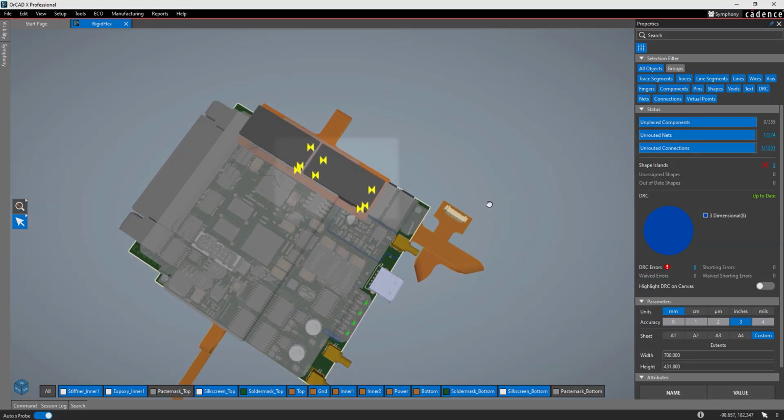These yellow DRC markers indicate collisions. At the full bend angle, the pins from the LCD in this zone hit the top cover and the chips below it. Bend locations, radii, and angles can be adjusted to correct this as required.